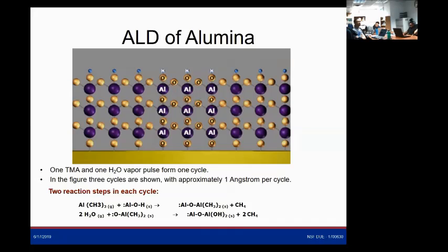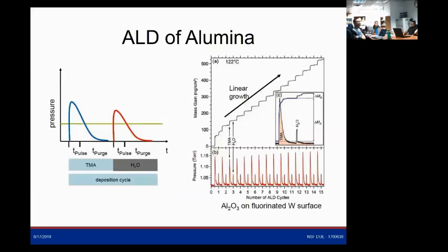So your research will be about those trapped charged particles inside the alumina. You will compare the concentration of these charged particles and defects. Let's say this oxidation was not completely done. Okay, so that's going to create a defect. You're going to electrically and optically characterize that with respect to a thermal oxide, oxide that's grown in a furnace.